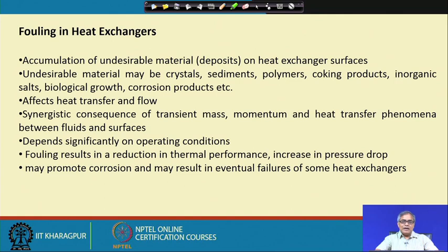Let us say in a plant there is a circulation loop, and in that circulation loop somewhere we have a filter. Now, the filter is not operating properly. So, then what will happen? My operating condition has changed, and depending on my operating condition, I will have different aspects of fouling present.